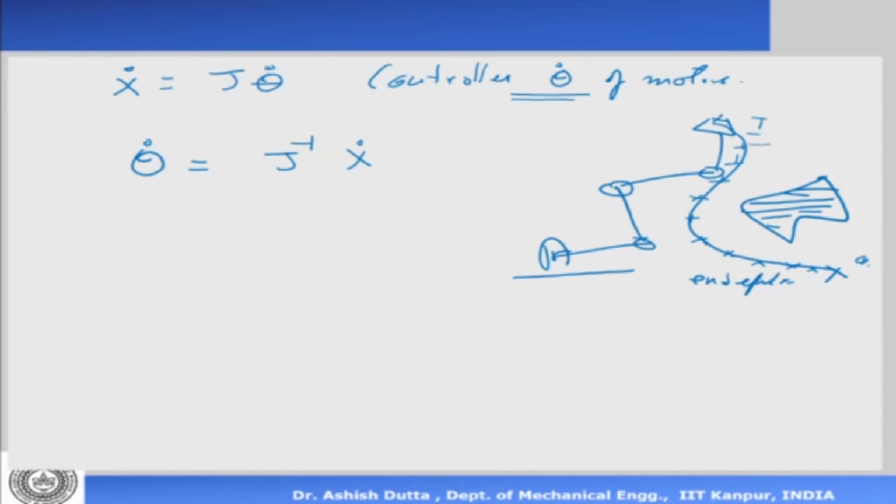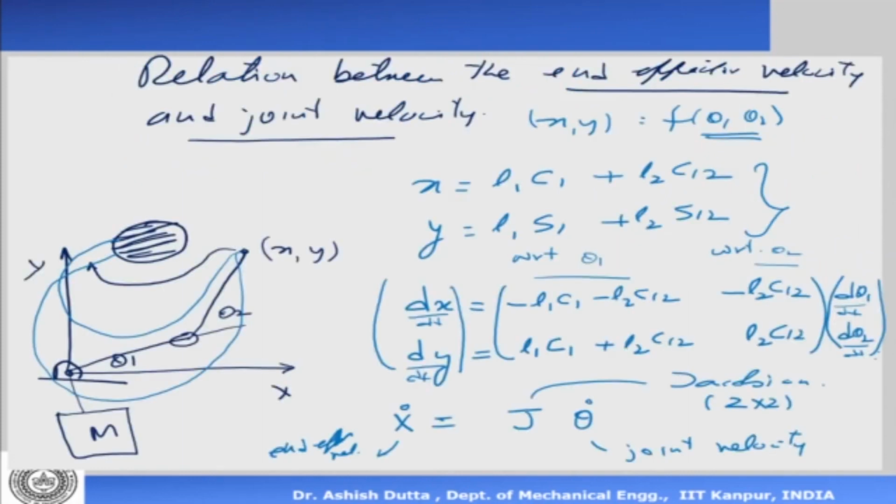So I will be able to get the corresponding angles, theta 1, theta 2, and maybe there are theta 4s. For every point here, it has to do inverse kinematics and find the corresponding joint angles. Then the difference between this and this is an incremental velocity. This is something I forgot to mention here, that this is an incremental velocity. These are incremental velocities and not average velocities.